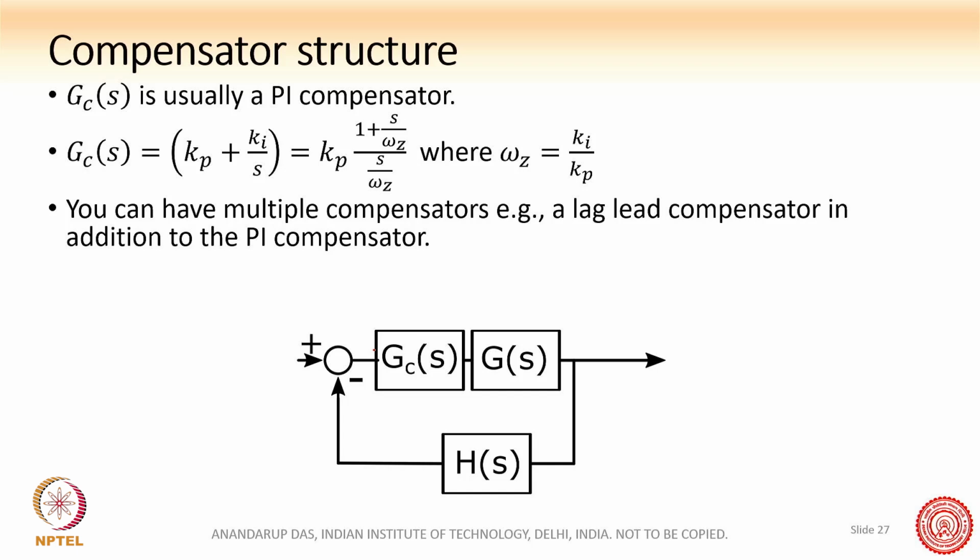Other types of compensators can also be used, but generally we have seen that the PI controllers can give a very good performance, okay, sufficient for our purpose. In some cases where there is single or double frequency, suppose 100 Hertz oscillation coming, then a PR controller can also be used. PR controllers work very well in a narrow band of frequency, okay?